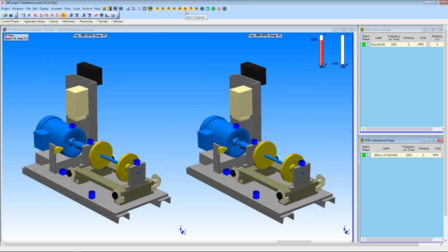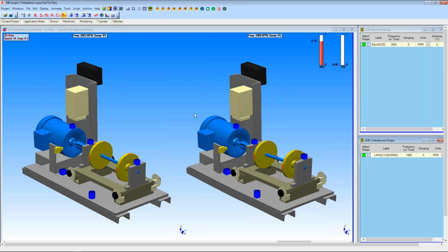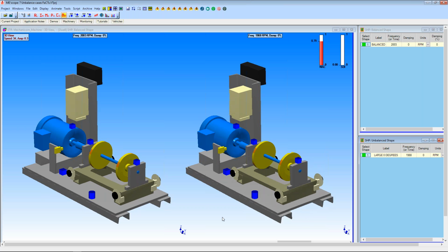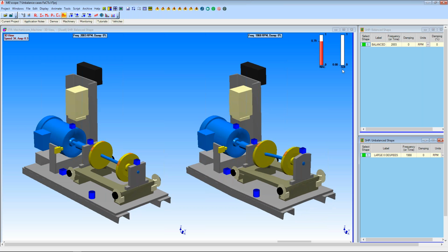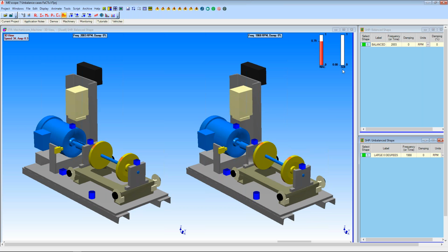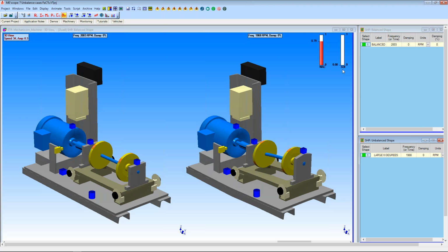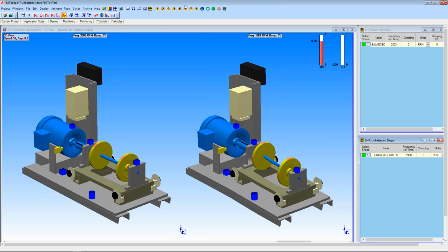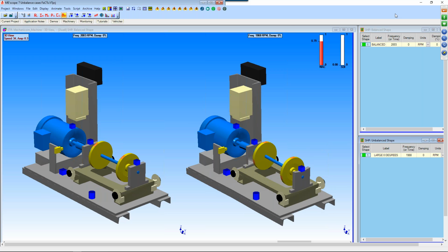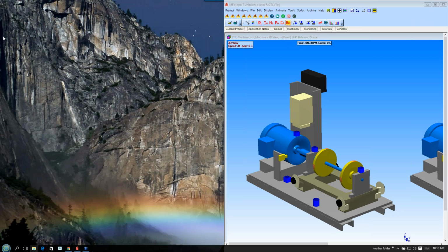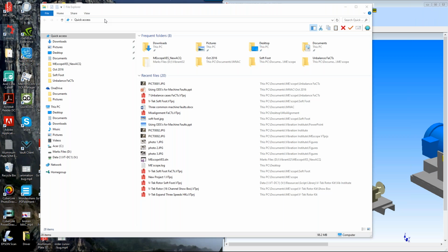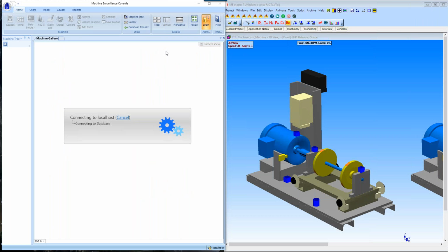Let's go to the worst case here. Both unbalanced weights at 0. These are large weights at 0 degrees. And so you can see the loose end here of this thing is really moving around. The MAC value didn't change a whole lot, but the SDI value is a good discriminator of the difference in these two shapes. Okay, so let's go and drag these over here, and now I'm going to show you how we can diagnose the difference, or let's say diagnose the machine fault by looking at these differences.